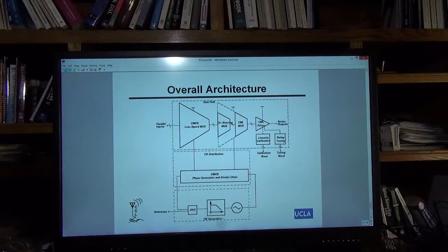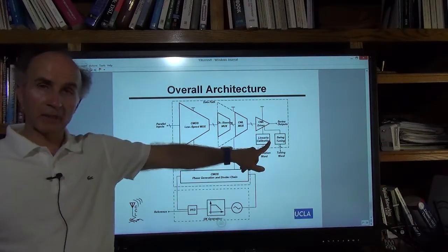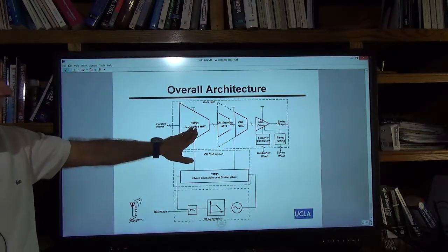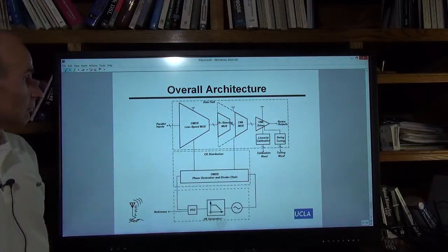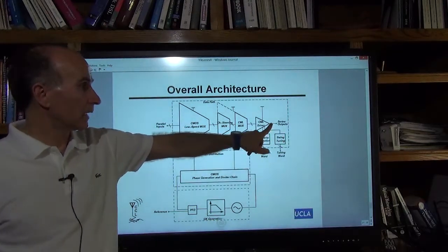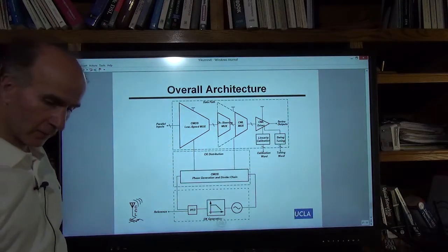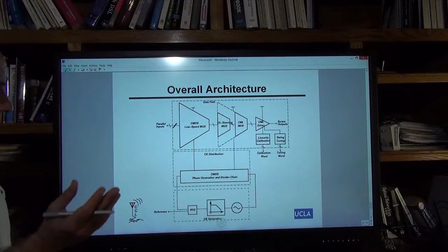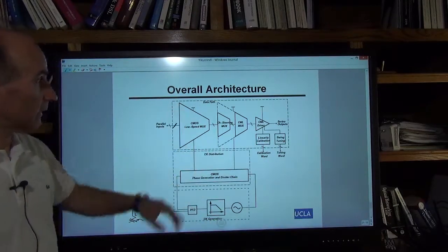Okay, so here's the same problem. Calibration is running into this line. So in fact, this N now looks like an R because part of the N is missing, right? So that shouldn't happen. The text has to be not italic. It should be Roman, all that stuff. Parallel inputs, series outputs. If it's outputs, it needs a line here. By the way, this line should be the other way. So it should be this way, not that way. If you want to indicate multiple logical lines coming in, it should be that way, not the other way. Okay. And again, all the spacings, everything else as we said before.